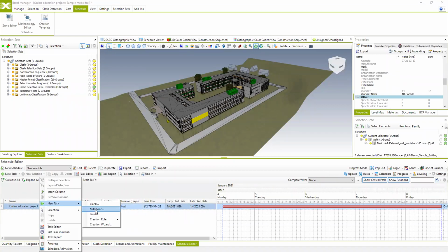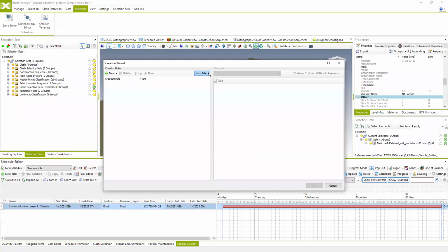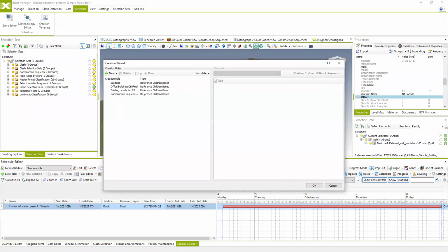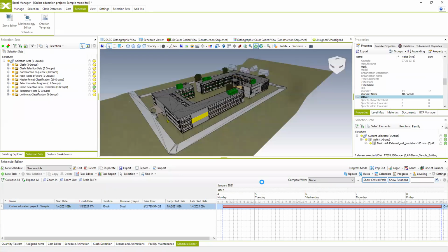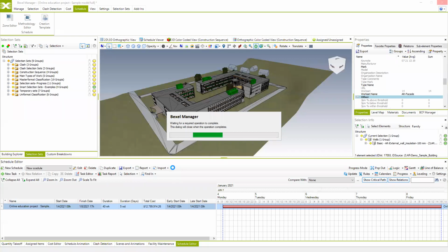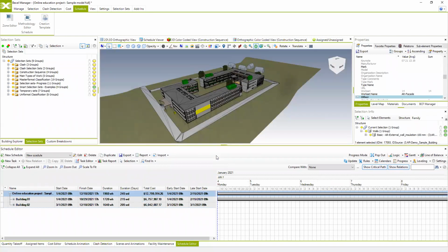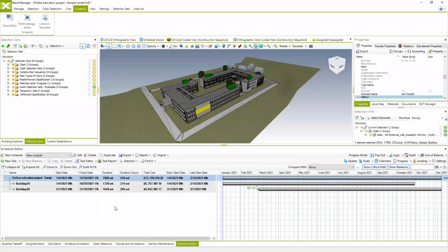And when we do that, the system will automatically create an entire schedule with a lot of tasks and relations between these tasks, and automatically all these tasks will be related to 3D BIM model elements in order to create a 4D simulation, but not just a nice video of your schedule, it's also an accurate, feasible and optimized schedule which you can use on your real construction projects.